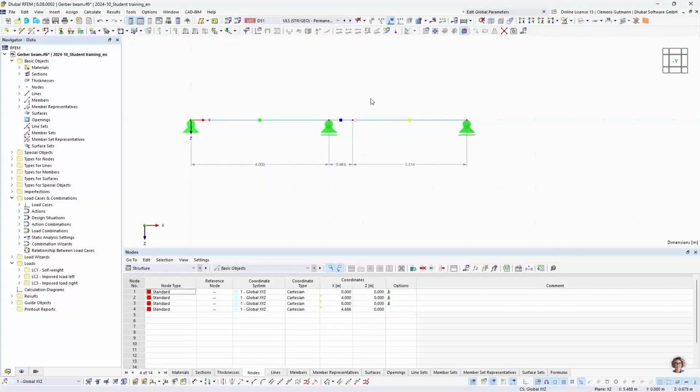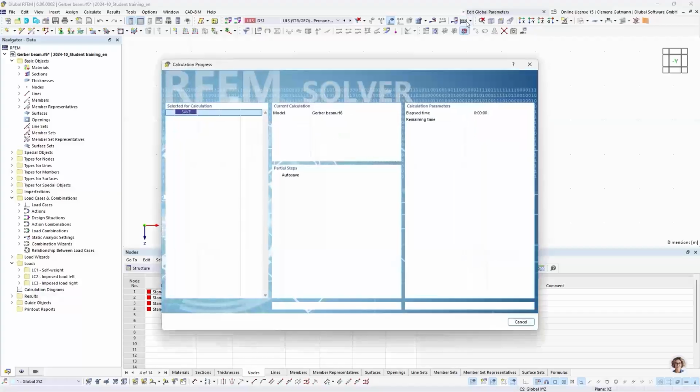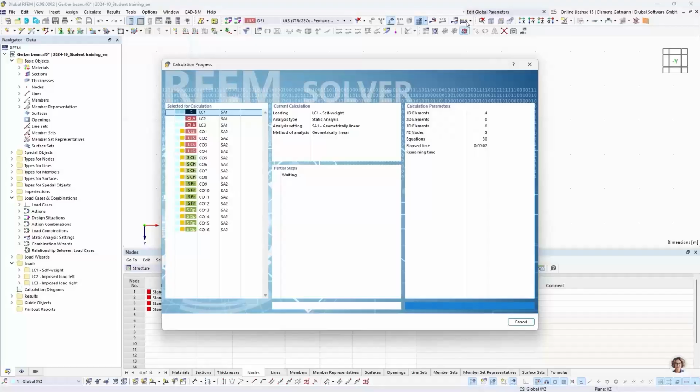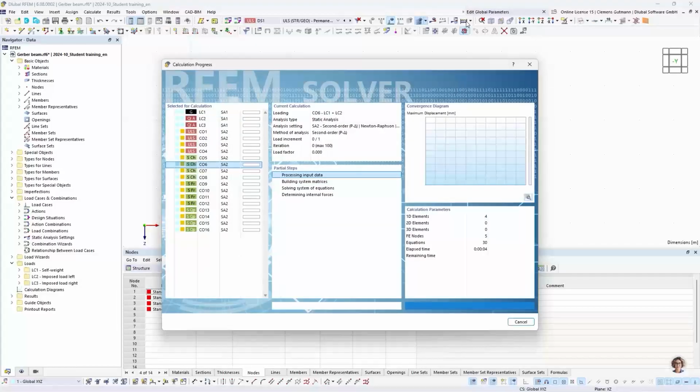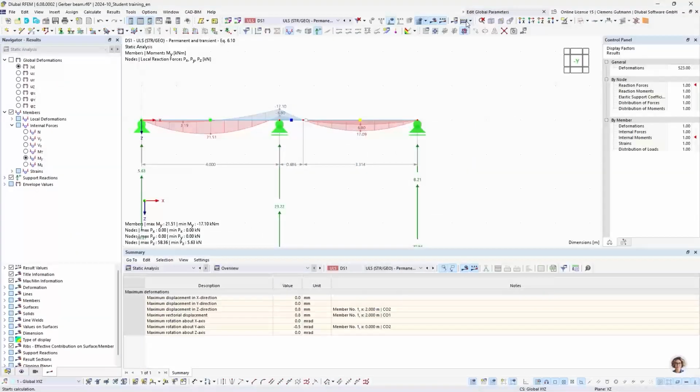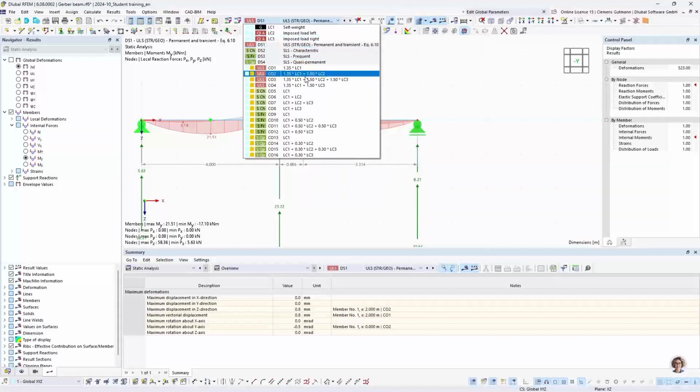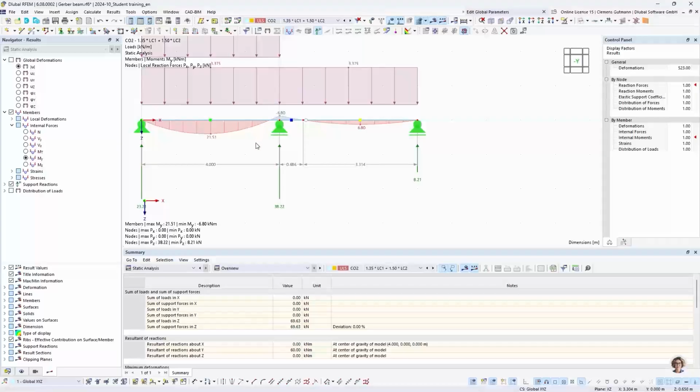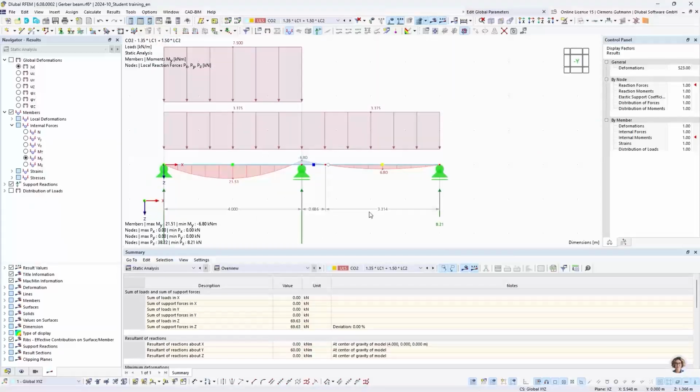And now we can calculate the model again and see whether the statement that the center bending moment and the field moment are the same value can be proven here. So let's see, for example, well, it is partly true, but this is just because the statement with the same bending moment values only is valid if the load is evenly distributed.